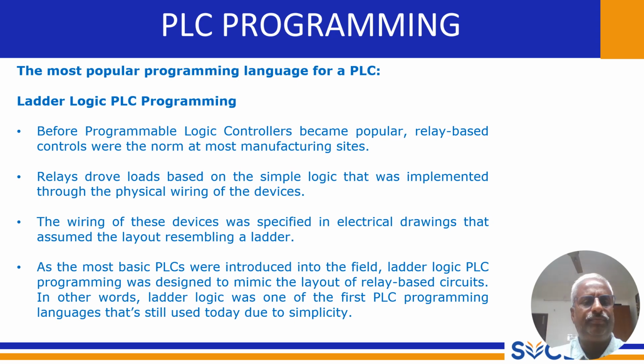The ladder logic programming method, before programmable logic controllers became popular, as I said here, relay-based controls were normal at most manufacturing sites. Relays drove the loads based on the simple logic that was implemented through the physical wiring of the devices.